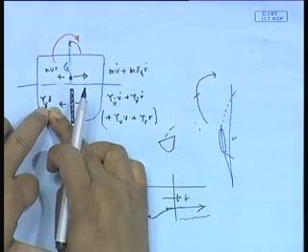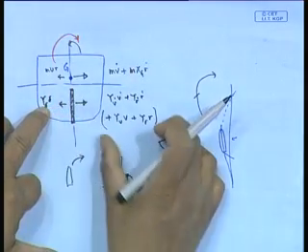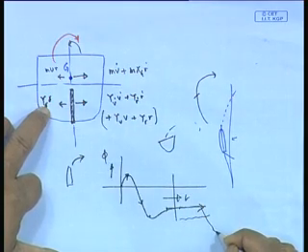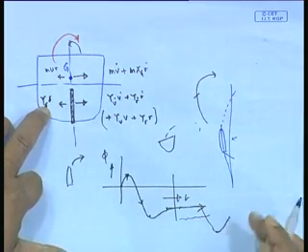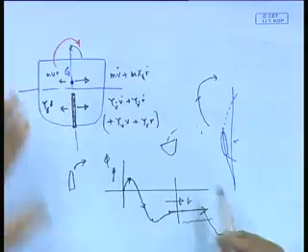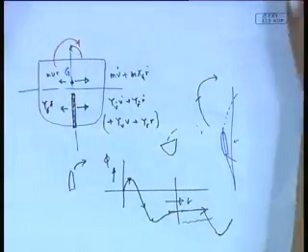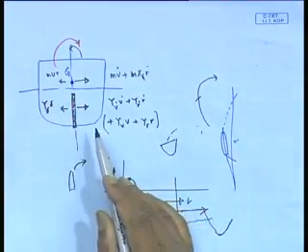Now, suddenly I make this 0. What would happen? This suddenly becomes more, so the ship is going to have a snap roll outside. It is going to roll further instantly, and therefore it may capsize. I will show this with respect to an equation form, but I just want you to see the physics of it.